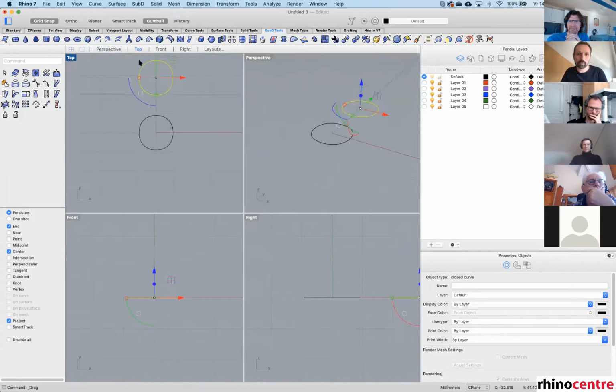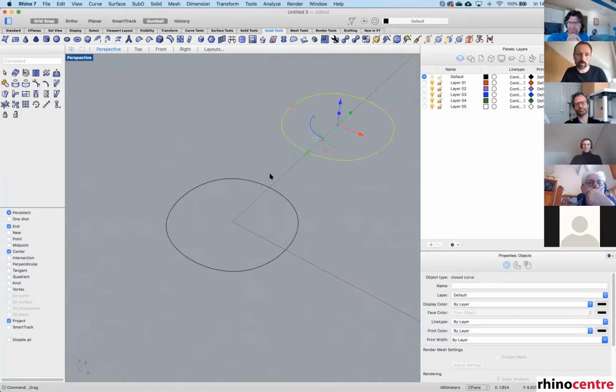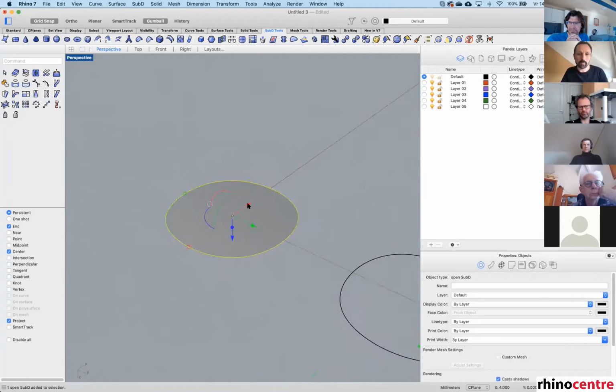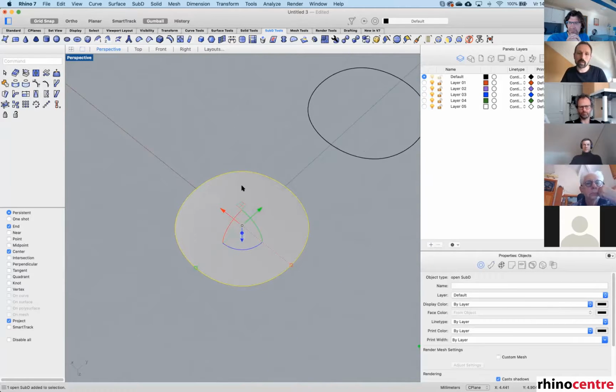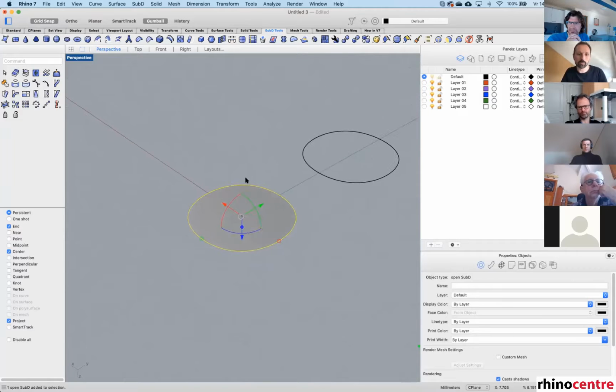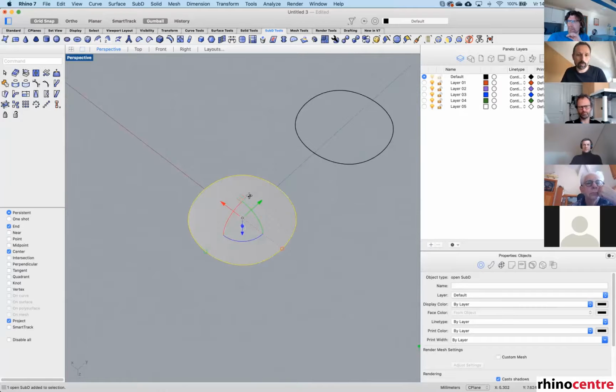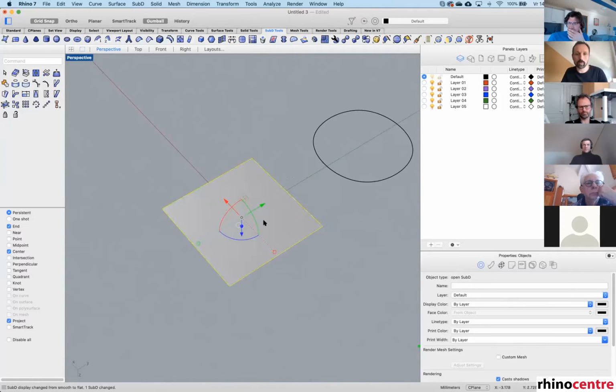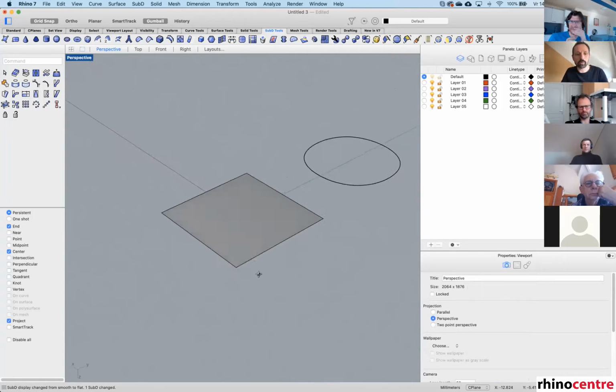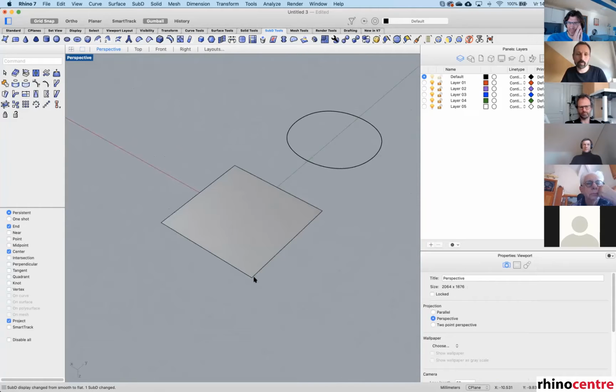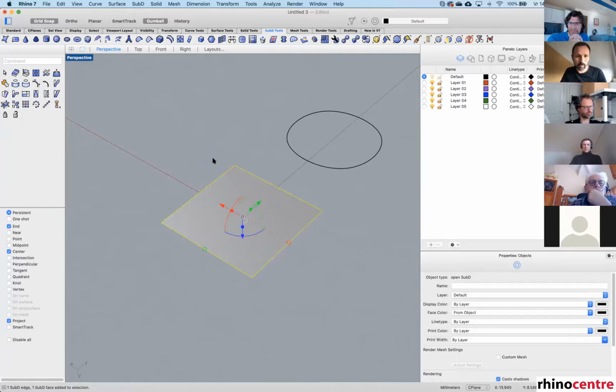Now these subdivision surfaces, I'll shade my view here, are objects that can be modified based on control points, edges, and faces. When you have an object in subdivision surface, you can switch between the so-called smooth mode and box mode with the tab key. If I now Control Shift Select, or Command Shift on the Mac, is that correct?